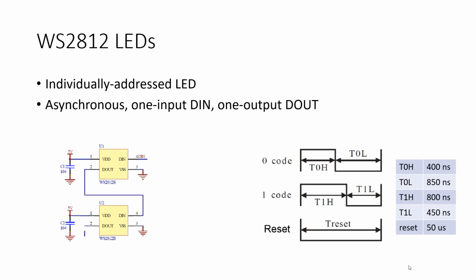In other words, the high and low cycles is 15 bits for each one, and it really only needed to be 2 bits because there's only 4 options. But obviously the peripheral is general purpose, so you have to explicitly put in the high and low time for each bit.